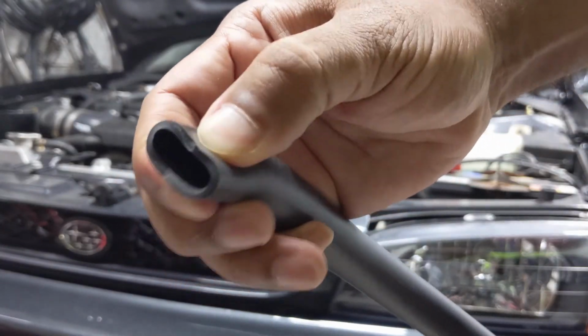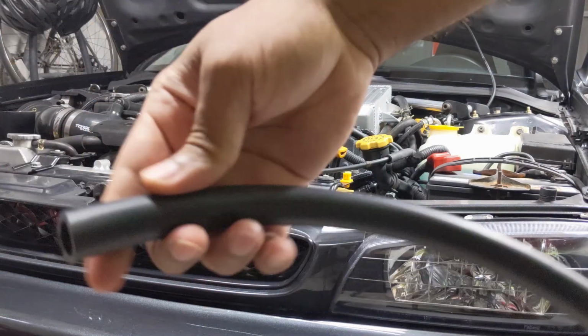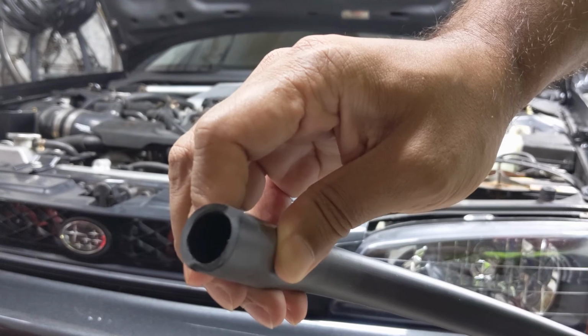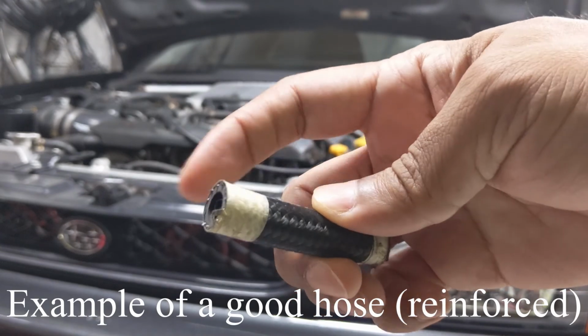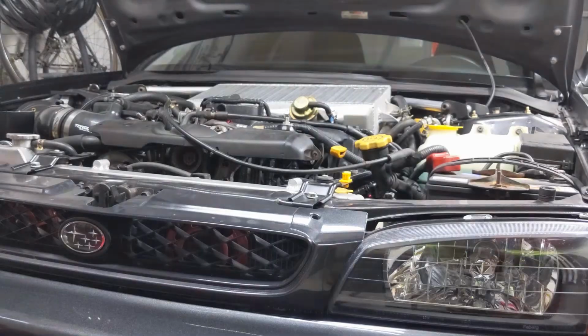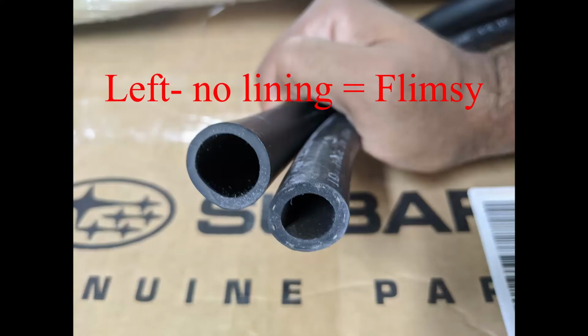Flimsy hoses with thin walls will most likely collapse under vacuum and burst when pressurized. So get the reinforced products for your intake, boost, and cooling systems. And also, cheap and flimsy hoses will fail when they're exposed to heat or chemicals. So if you plan to upgrade your PCV, vacuum, coolant, fuel hoses, or piping, make sure you have the material that is designed for that application.